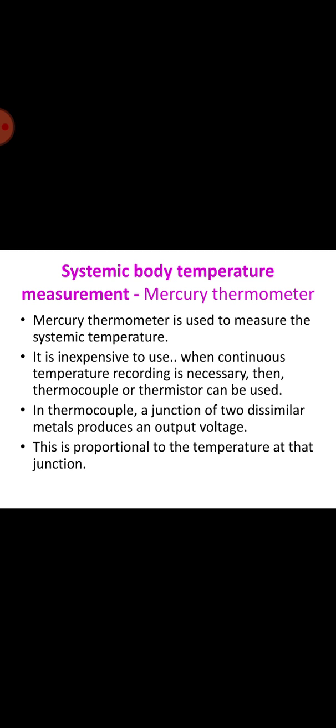The grounded thermocouple is the most commonly used style. A thermocouple is grounded when both thermocouple wires and sheath are welded together to form one junction at the probe. Grounded thermocouples have a very good response time because the thermocouple is making direct contact with the sheath, allowing heat to transfer easily. A drawback of the grounded thermocouple is that it is more susceptible to electrical interference.